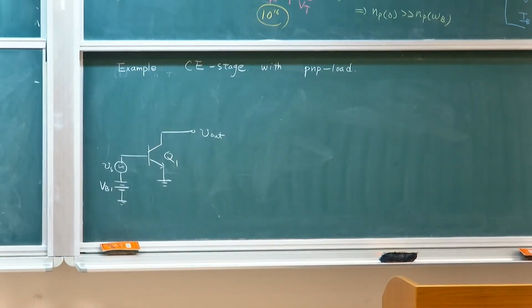Right? Remember when we derived the circuit, we simply added a loading resistor, which is an RC, on top. But instead of having an RC, one of the things you need to understand is that in an integrated circuit, it's very hard to deliver a passive component. It's very costly. So if you wanted to deliver a load, the load simply meaning that I want to transform current into voltage, I simply use a resistor.